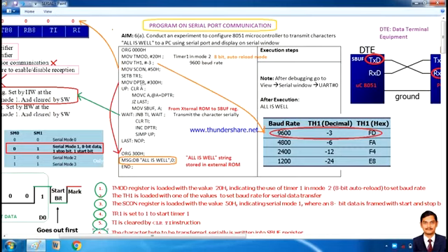Next, clearing the accumulator. Since I am going to use indexed addressing mode to access each character, I am going to clear A. This is the first step we have to keep in mind: for indexed addressing mode, the accumulator must be cleared. MOVC indicates the external ROM is accessed.